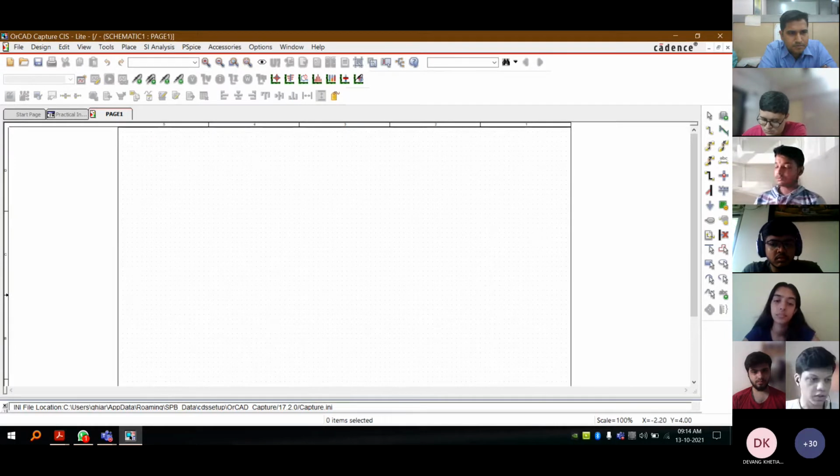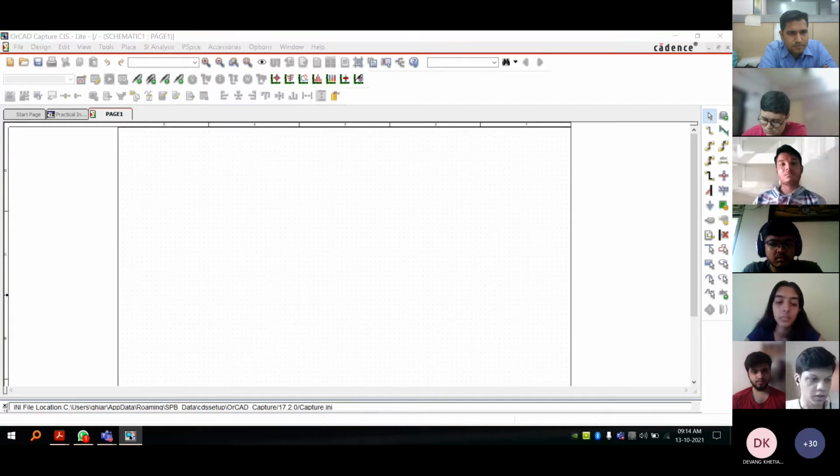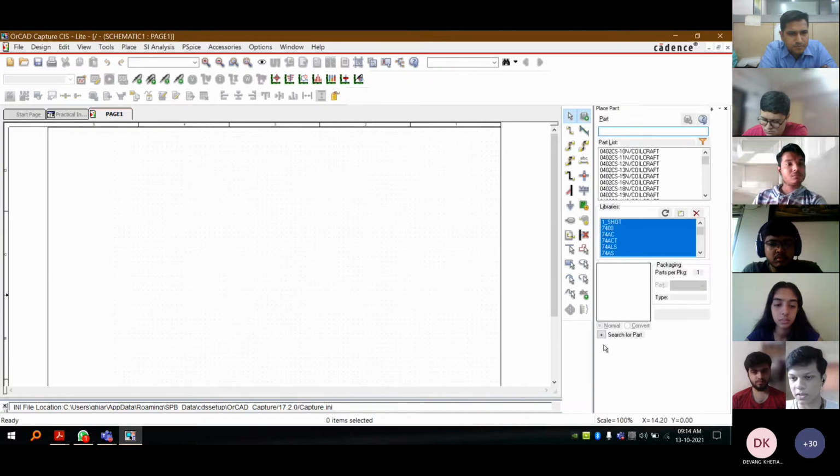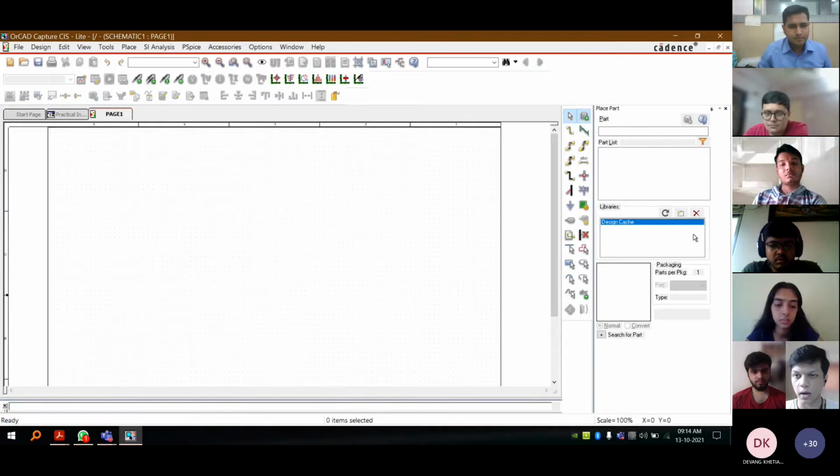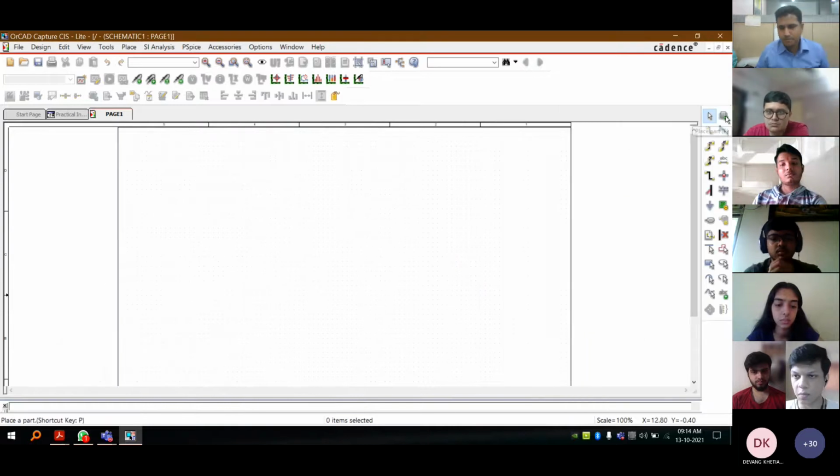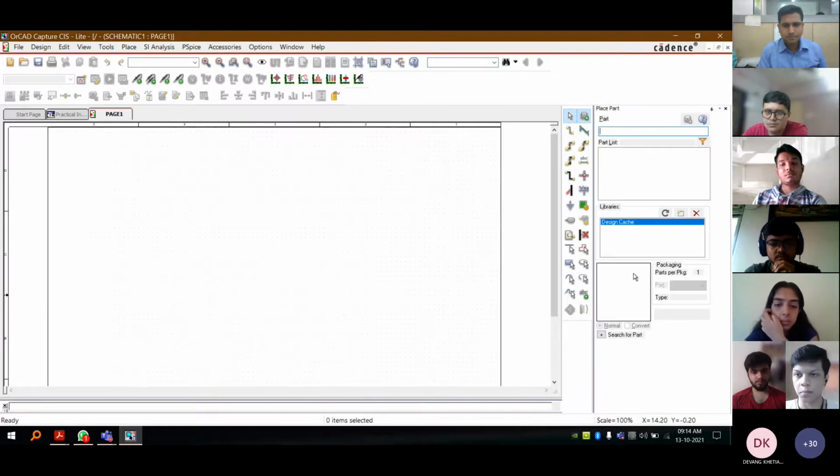All right. So in order to create an integrator, what we're going to need is our op-amp. One good thing about OrCAD that I love is that all of the op-amps that you need are already going to be ready. So I'll show you what you guys are going to see when you start OrCAD up. What you need to click is this button over here called Place Part. When you click that button, you will most likely see a screen somewhat like this.